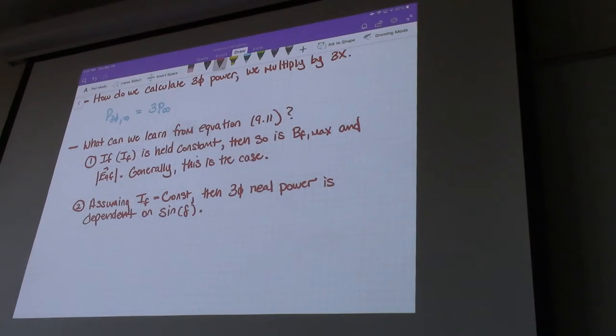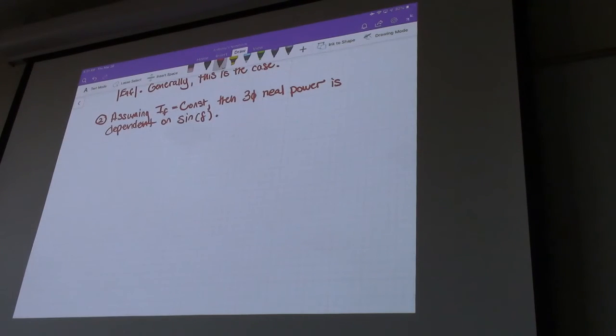And if you think about this in physical terms or practical terms, we know that if we're not changing the mechanical input, the power is being converted into some combination of real and reactive power. So the more real power we have being generated, the less reactive power, more or less, and vice versa. So not having much real power being generated is not a good thing.